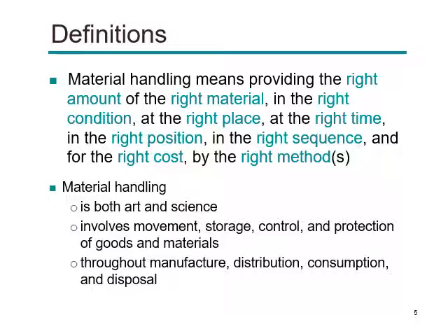If you move more than necessary, it means that those items need to wait in that department, which is a WIP inventory, and it will need space in that department, and it will increase your WIP costs. If you send less than necessary, then your production can stop due to lack of parts.